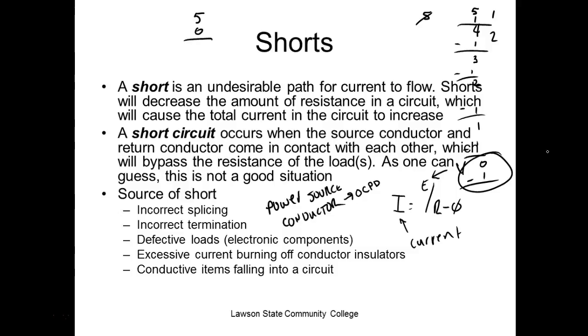Most everybody's had a short circuit in their house. And Alabama Power don't want to give up. You know, Alabama Power can put out gigawatts worth of power. So who's going to give up in your house if you have a short circuit? Your wires. And what are they going to do? Yeah, cause a house fire. So definitely in your house you need an overcurrent protection device, either a fuse or a circuit breaker, right?